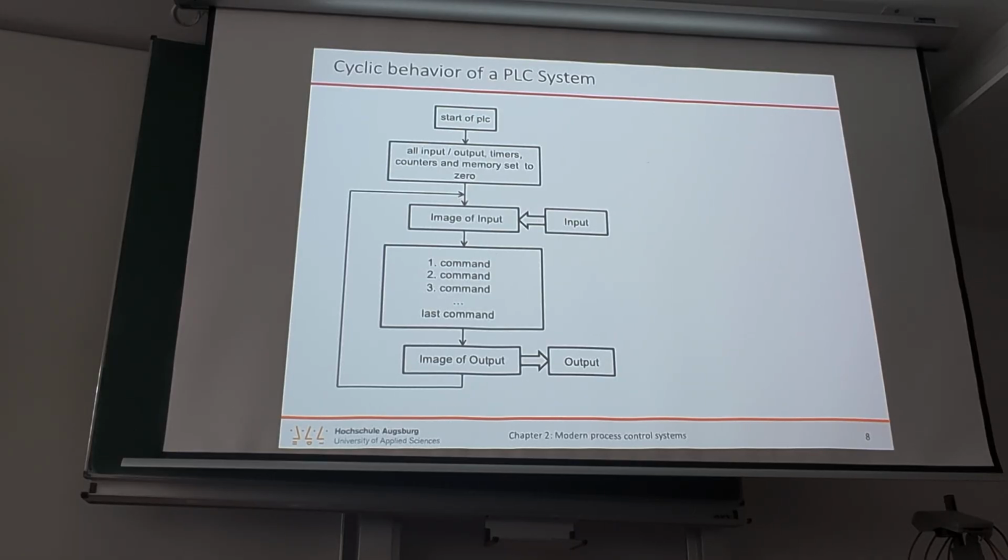Yeah. What language is typically used in PLC? Is it proprietary? So Siemens has their own language? Yes, it is. Okay. It's not proprietary, it's a standardized language. There are 6 languages in the IEC 61131-3, and in the updated version there's only 5 left.